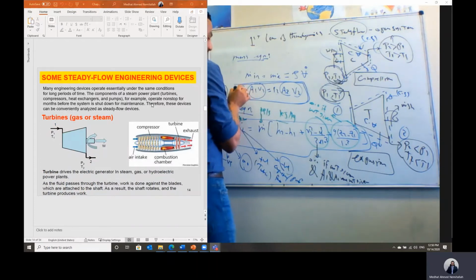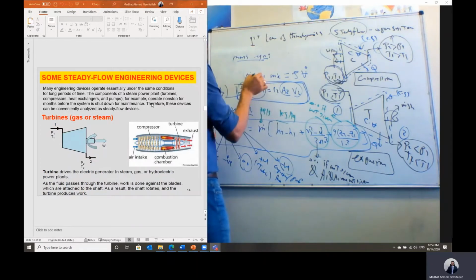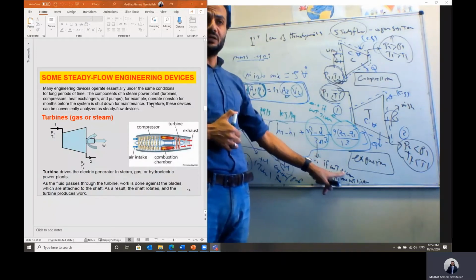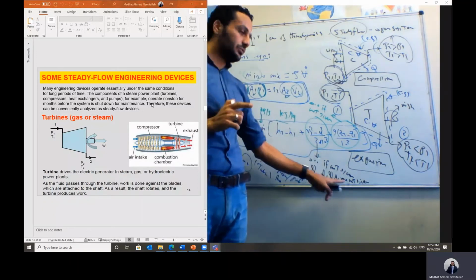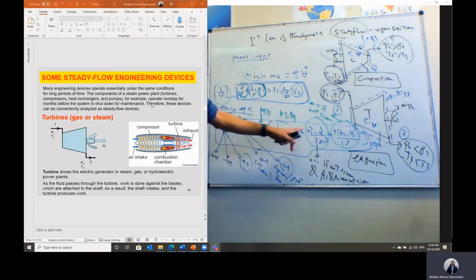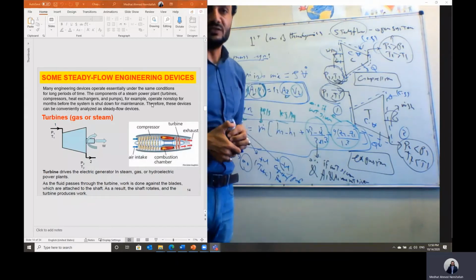In this case the mass flow rate will be given, and the density we can calculate. If the density, area A1 and area A2 are given, then using the mass equation, equating m dot to density times area times velocity, we can calculate the velocity V1 and the velocity V2. So, this term will be 0 if not given or required, and the areas A1 and A2 are not given. But if he gives you the area A1 and A2, then we can calculate V1 and V2 based on the mass equation.